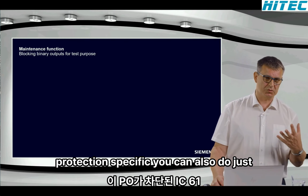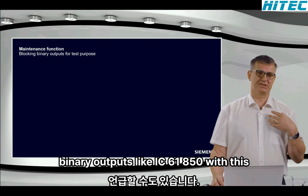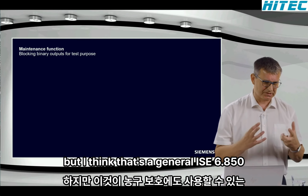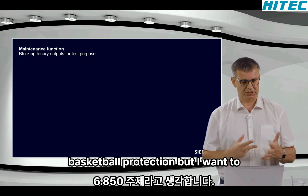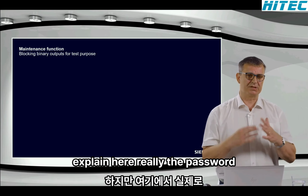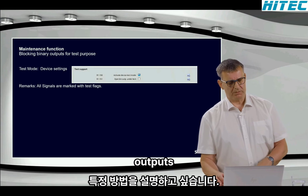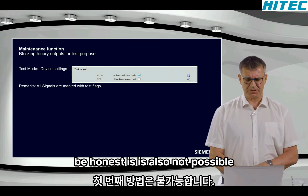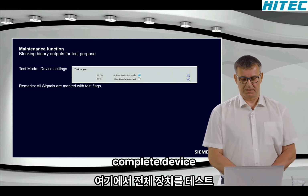You can also do, just to mention it, this blocking of binary outputs like IEC 61850 with this BO blocked and so. That's also possible, but I think that's a general IEC 61850 topic. This can be used also for busbar protection, but I want to explain here really the busbar protection specific ways to block binary outputs. The first way, using the test mode, to be honest, is also not busbar protection specific. You can activate the test mode of the complete device.